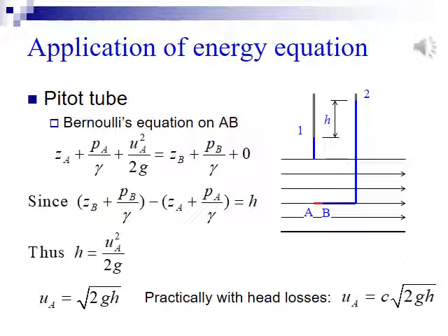I almost forgot one thing in the energy equation. Please forget absolute pressure in flow problems. We only use gauge pressure in our calculations because all flows that we discuss here are surrounded by the air, and atmospheric pressure doesn't contribute to our flow.